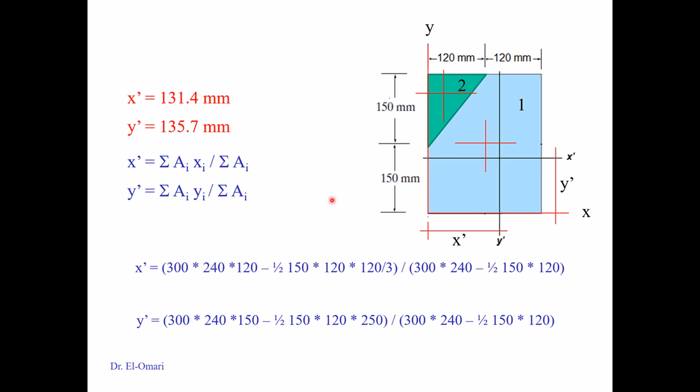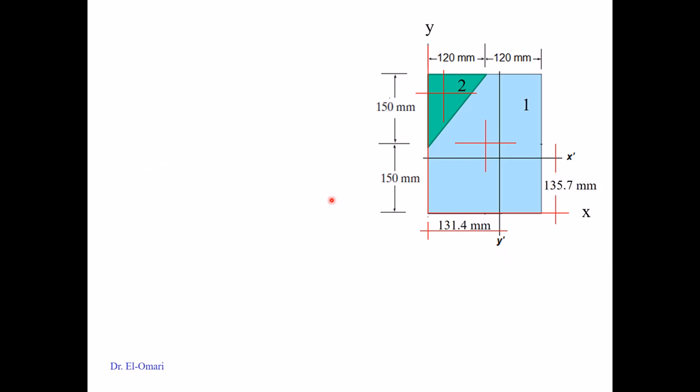So next is to find the moment of inertia of the whole cross section. To find it, we'll use the same division that we did: a big cross section, and then subtract from that the moment of inertia of the smaller cross section, for both axes.